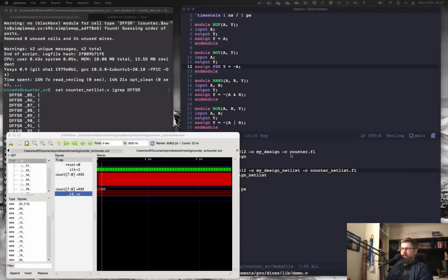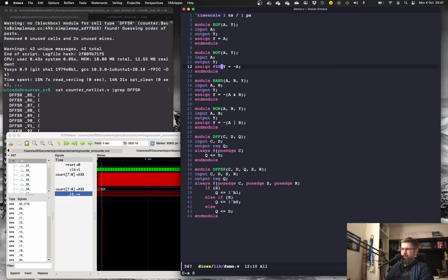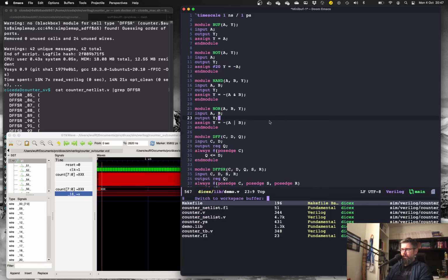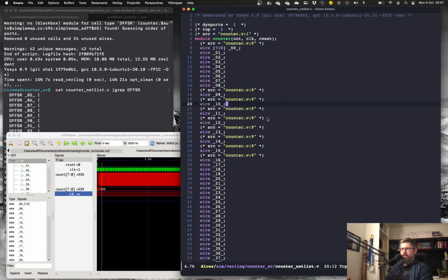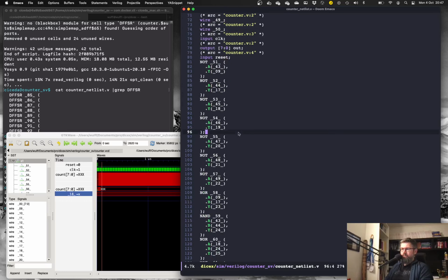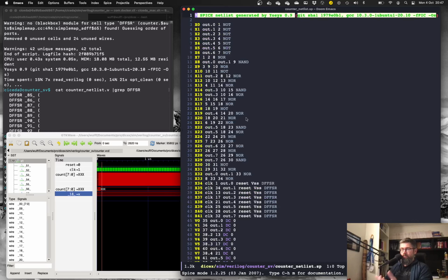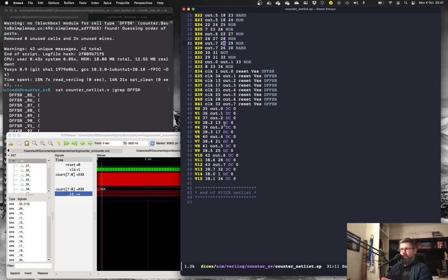When you're ready, you can then do the layout, because you could actually do the layout manually for this netlist here. It takes a bit of time maybe, but it's not that hard. And if you wanted to, you could also run spice simulations. So if you have a spice library for your library cells, this is a spice file that is the same thing.